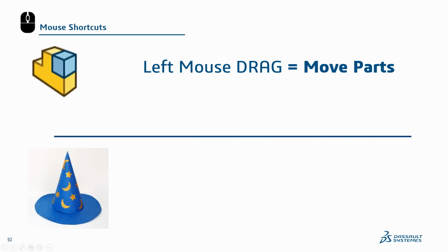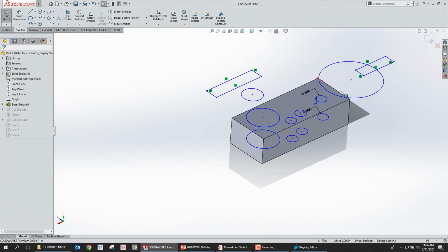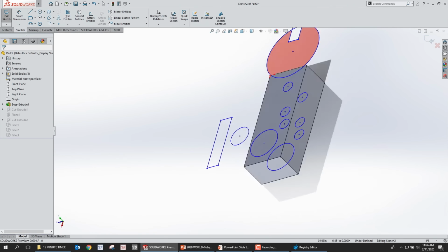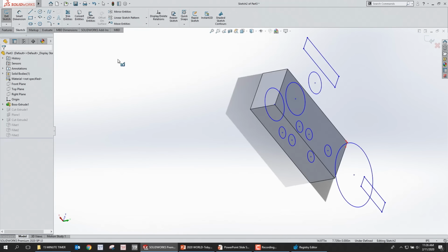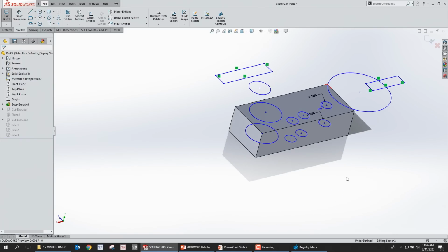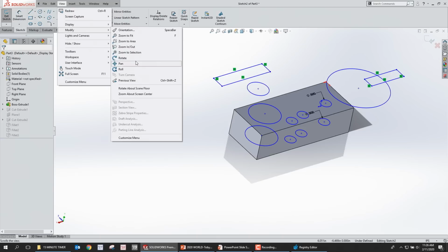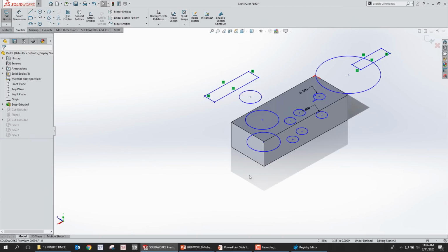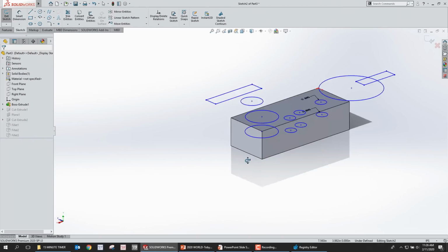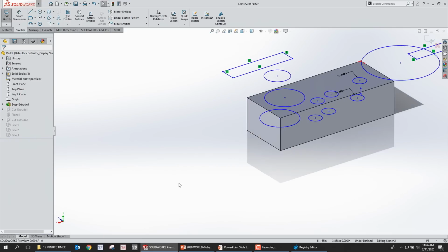Yes, question. Oh yeah, that's a good one. So, Alt and drag for the barrel roll. Yep. Like change where you're rotating about. Yeah, I mean, there is that rotate about scene floor also in view modify. So you've got this view modify, rotate about scene floor. Maybe you could use that to your advantage. Set the scene floor to something that you want. Yeah.